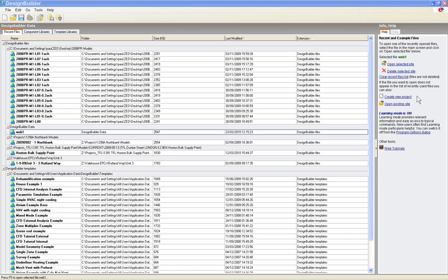carry out some simulation using EnergyPlus, and then I'm going to use the link between EnergyPlus and the CFD module to import data from one to the other, and then we'll be able to look at the actual flow throughout a room using the CFD element. And how we can get some graphical output and how we can use that to analyze our buildings.